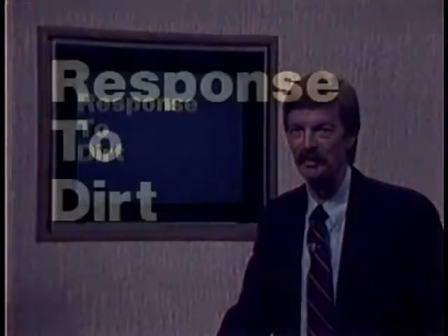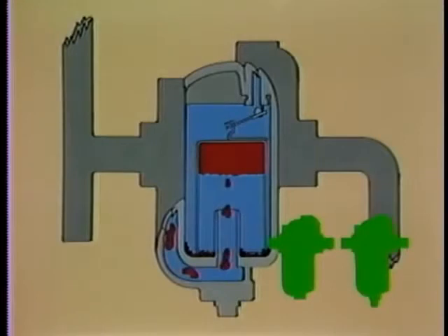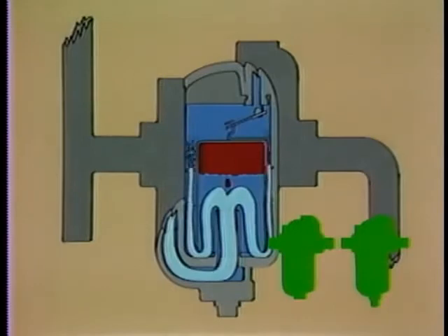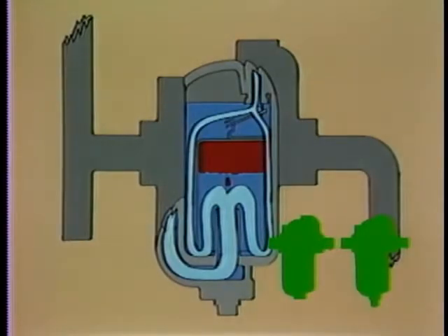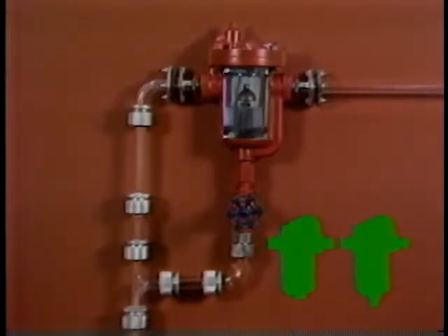As condensate flows through the system, it picks up dirt and scale formed on the walls of the piping, as well as any solids that carry over from the boiler. Traps must be able to operate in the presence of this dirt without damage to or blockage of their orifices or mechanisms. The intermittent discharge of IB and DC traps create a self-scrubbing effect at the bottom of the trap. Dirt particles smaller than the orifice diameter are flushed from the system. With the orifice located at the top, dirt, scale, and other matter settling to the bottom of the trap will not plug the discharge port.